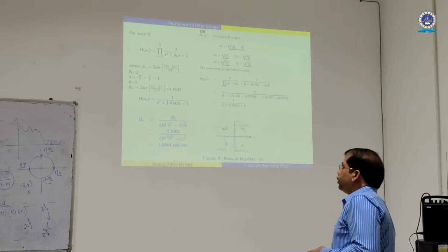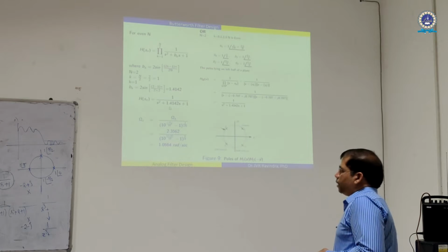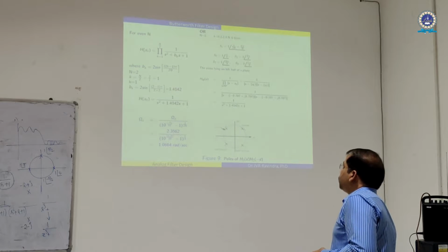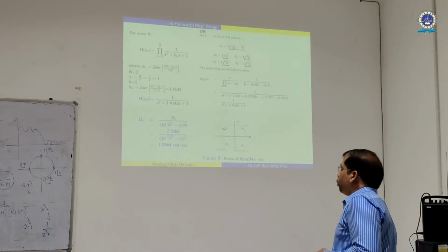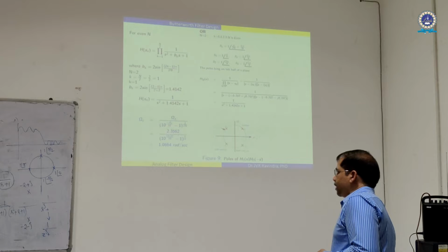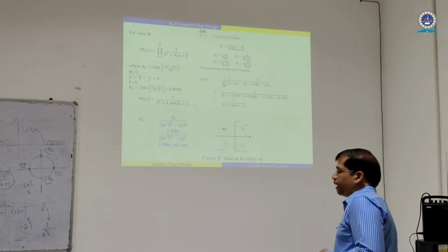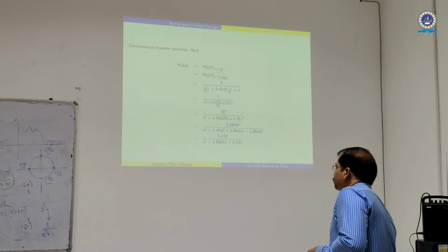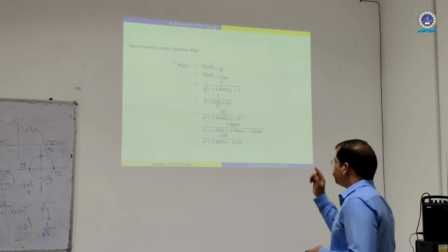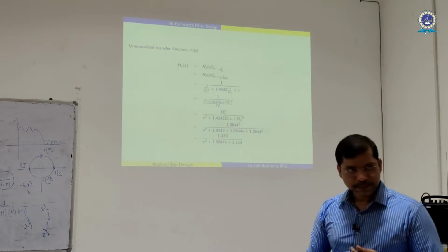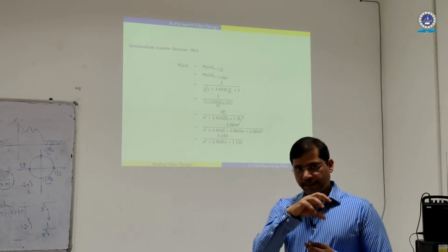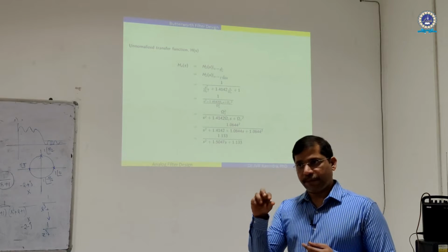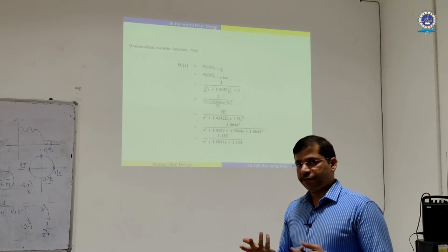If n is even, this is the equation that you can apply, but you will land on the same value. Or else, understand n equal to 2 and apply the poles, but if you simplify this, you get the same value. So either this procedure or the direct value, anything fits correctly. So now you can apply this. From that, that's what the Butterworth said, for n equal to 2, 1 by s square plus root 2 s plus 1. But where are we using our values?